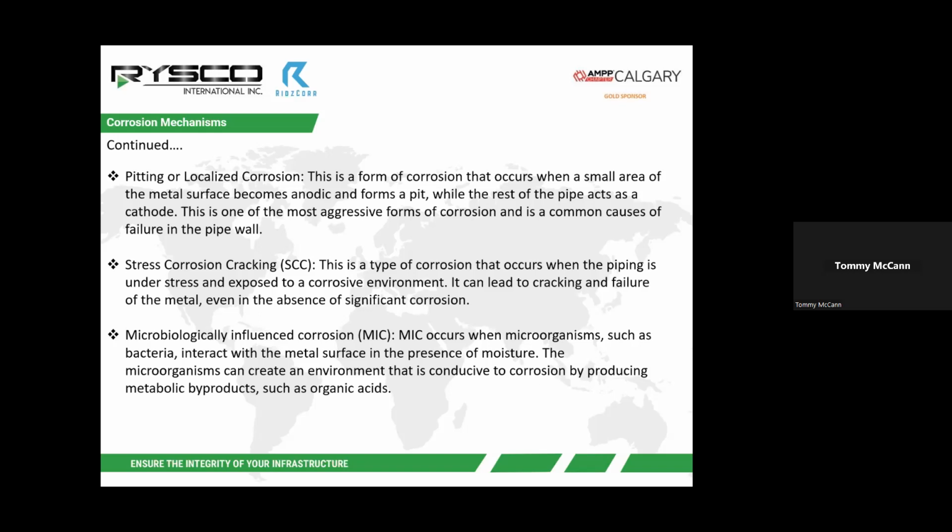Stress corrosion cracking, it's not one I deal with very often, but we do have some systems we manage here that we monitor for it. Basically, where you have stress on your pipe or piping, and there's a corrosive environment, you can see that cracking within the structure, and you have a very rapid failure, and it can happen very quickly because it doesn't need a lot of corrosion to cause that.